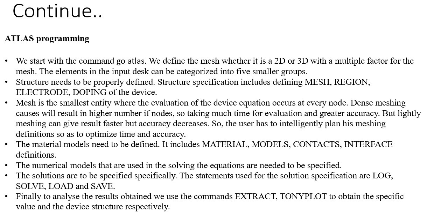Next is Atlas programming. Now you have to learn how you can easily program. First of all, we will start with the command go atlas. We use the Atlas simulator, so we will go for the go atlas command. There you have to specify whether you are using a 2D simulator or 3D simulator, along with the multiple factor for the mesh.